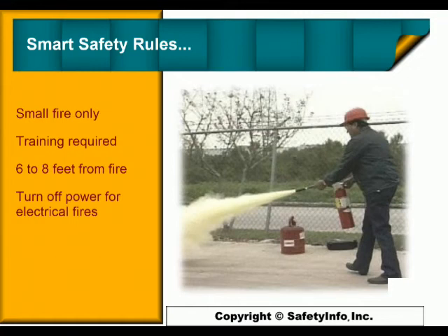Never place an empty or partially discharged extinguisher back in its location. Always replace it with a fully charged extinguisher. If you notice any damaged or missing extinguishers, please tell your supervisor right away.